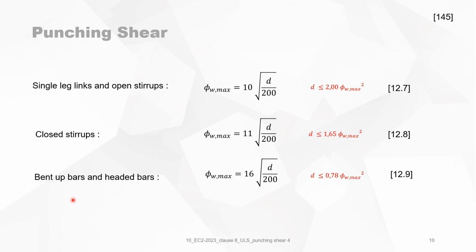So in fact, when one is designing slabs, you need a lot of information to make a proper design. You can have a total slab depth which is adequate for all the forces applied. And when you calculate the resistance for punching, it can happen that you need a bigger diameter of punching shear reinforcement, but this bigger diameter does not correspond to the chosen depth of your slab.